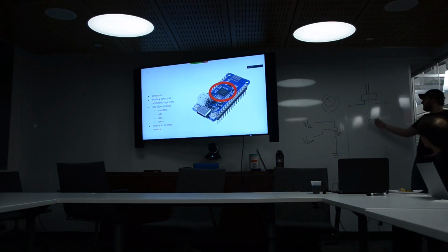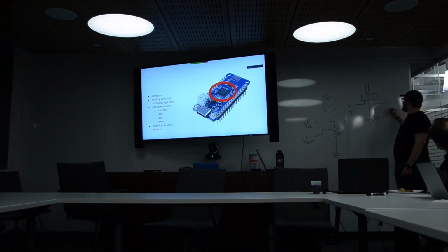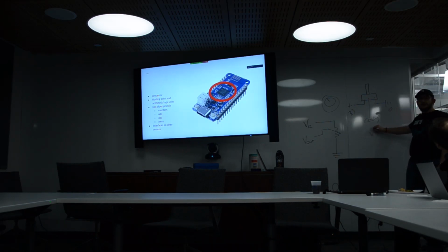So for example, in this one, if high is 3.3 and ground is 0, and we have a reading of 2.7, we can figure out by doing 2.7 over 3.3, oh, this must be 30 degrees to the left. Make sense? It all comes down to reading a data sheet, because the only thing that ADC can actually tell you is voltage.